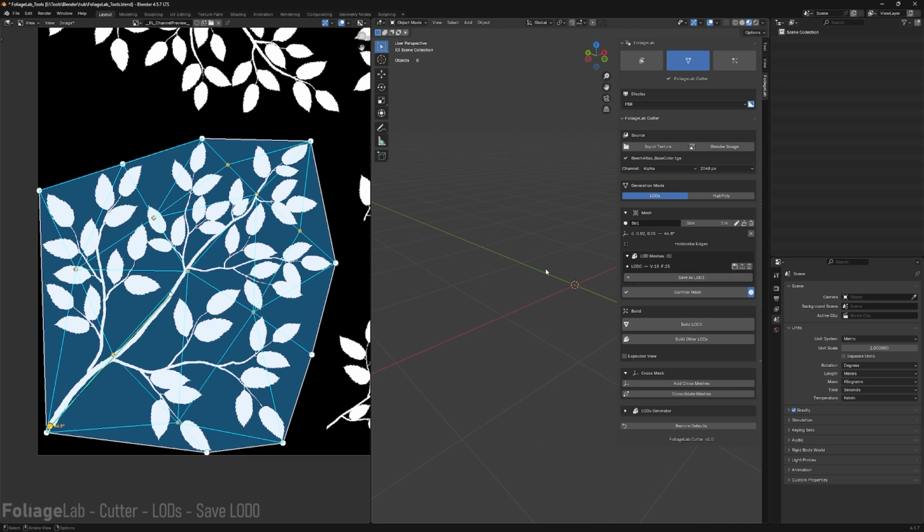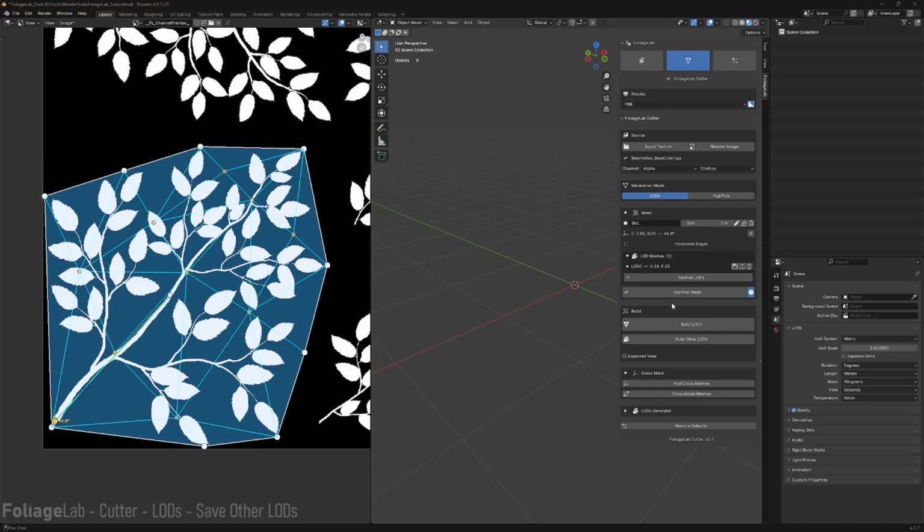And once it's done, you can simply remove some points and save your different actors as new LODs. Let's do this together and let's create at least 3 or 4 LODs together, and like that you will see the full LOD chain. Let's go. And for my LOD number 1, I just want to remove the inner point that I have here. So remember, keep pressing Alt and do a right click on each point you want to remove.